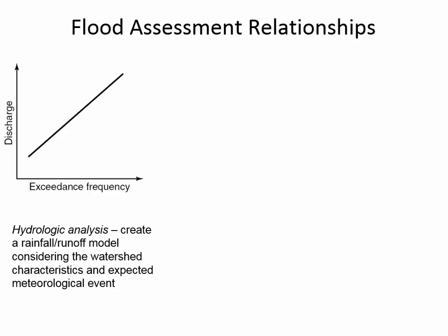And so the first one is, look at the x and the y figures here. So the x and y axis. Exceedance frequency versus discharge. Okay, so a certain storm frequency causes a certain flow rate. So this is what comes out of a hydrologic model. You've just been using WMS, right? And I told you to use a 3.2-inch storm for your analysis. And was that a 25-year storm? Did I say in the homework assignment that that's a 25-year storm? Okay, so basically, your model that you developed is able to characterize this curve.